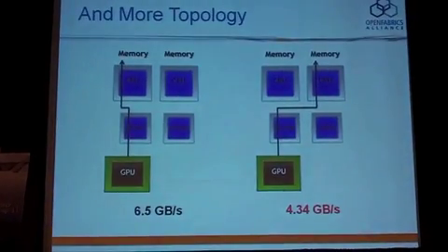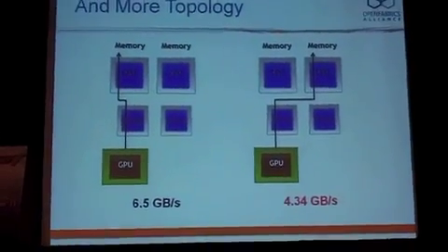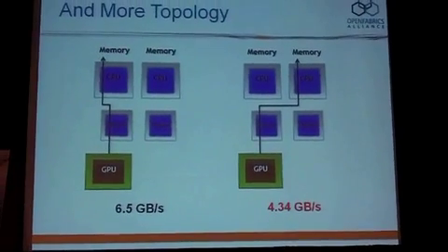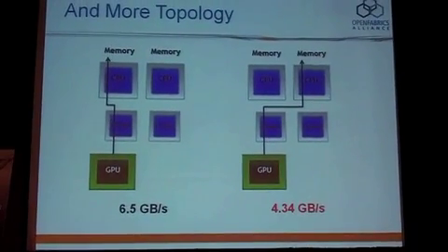So the reason that's interesting, right, is that numerically the bottleneck really should be the PCI Express bus. The memory bus is much faster. But for whatever reason, we don't see that performance. The bottleneck seems to be on the memory side of the bridge chips.